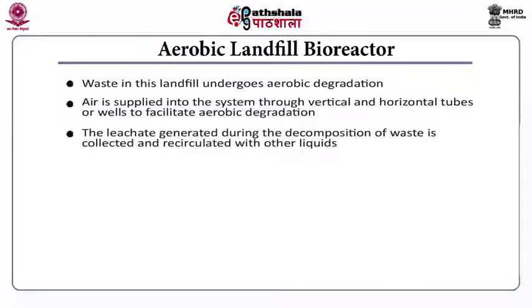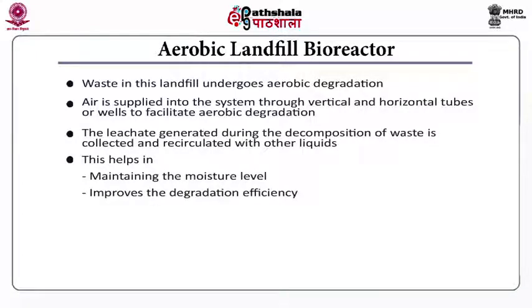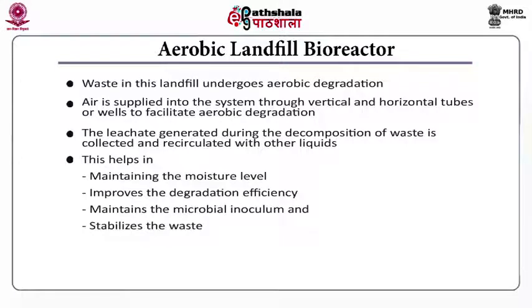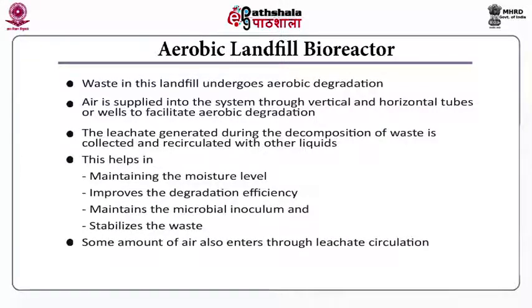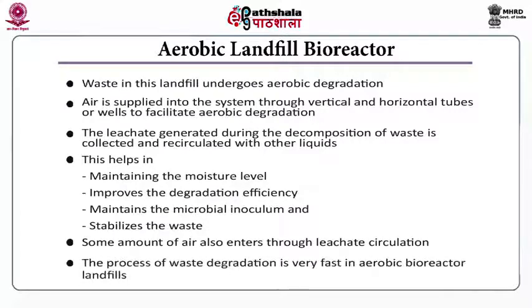The leachate that is generated during decomposition will be collected and recirculated with other liquids. This generally helps in maintaining the moisture level and thereby it will accelerate the degradation efficiency. Also, it will maintain the microbial inoculum within the waste mixture and it will stabilize the waste. Some amount of air also enters through leachate circulation, thereby accelerating the aerobic degradation. The process of waste degradation is very fast in aerobic bioreactor landfills.